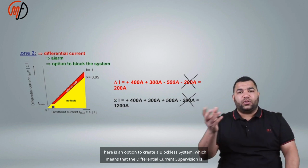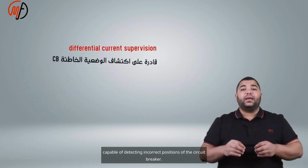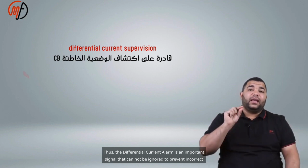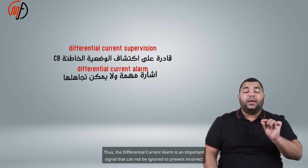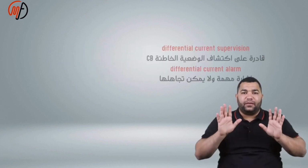There is an option to create a blocking system, which means that the differential current supervision is capable of detecting incorrect positions of the circuit breaker. Thus, the differential current alarm is an important signal that cannot be ignored to prevent incorrect operation of the relay.